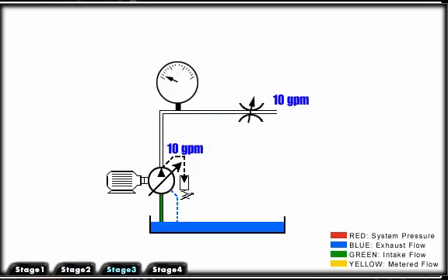With flow control used in a pressure-compensated pump, we do not push fluid over the relief valve. As we approach the compensator setting of 1500 psi, the pump will begin to de-stroke, reducing output flow.